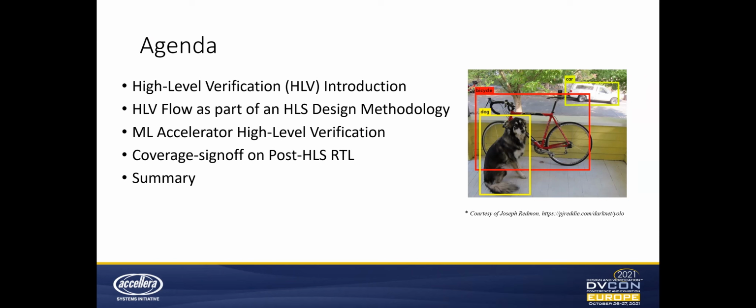We'll be doing all of this using techniques that many of you should already be very familiar with as verification engineers, but we'll be targeting the pre-HLS source code that was written in SystemC instead of the post-HLS RTL. Because the bulk of our verification is done against the pre-HLS source, there won't be much left to do after high-level synthesis, but we will go over what that would look like as well before we wrap up the tutorial.